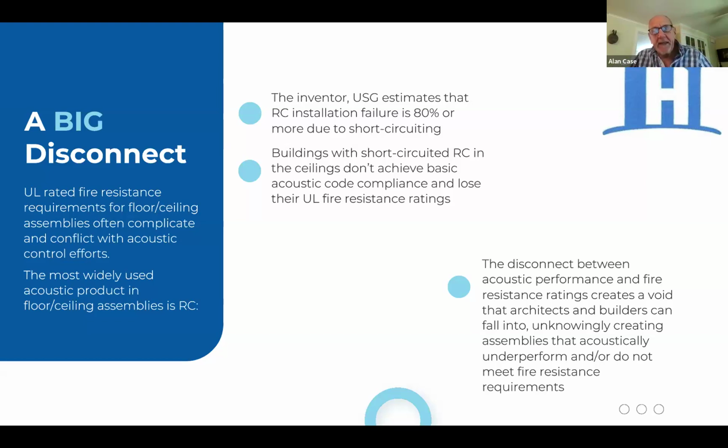And so to control that, UL requires, if you're in a fire rated assembly with these devices, that you put them in such an intense constellation that they can hold the channel to the frame while it's burning. The manufacturer of one of the clips will tell you that you should space them 24 inches apart in rows, and then every 48 inches along, skipping every other joist or every third, depending on your framing layout. So in a 12-foot by 12-foot room, under that formula, you would need 28 of their devices, and then the running lengths of the hat channel.